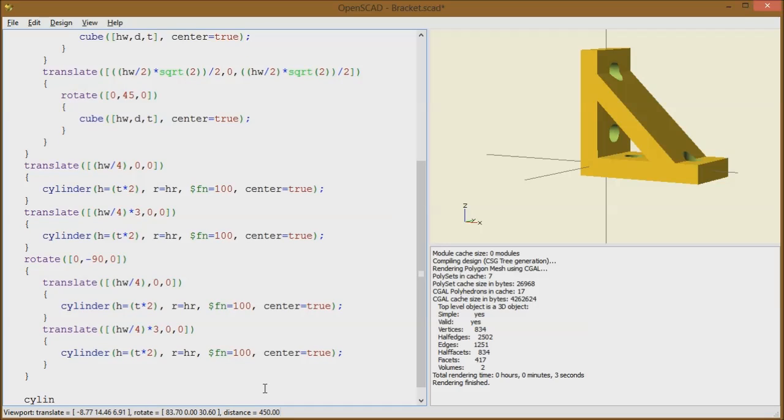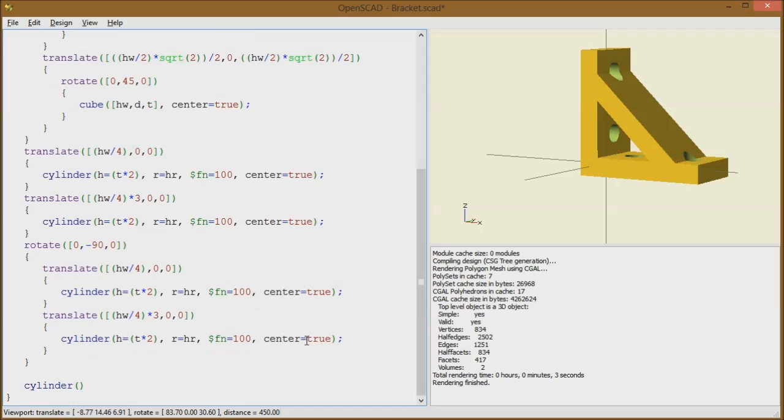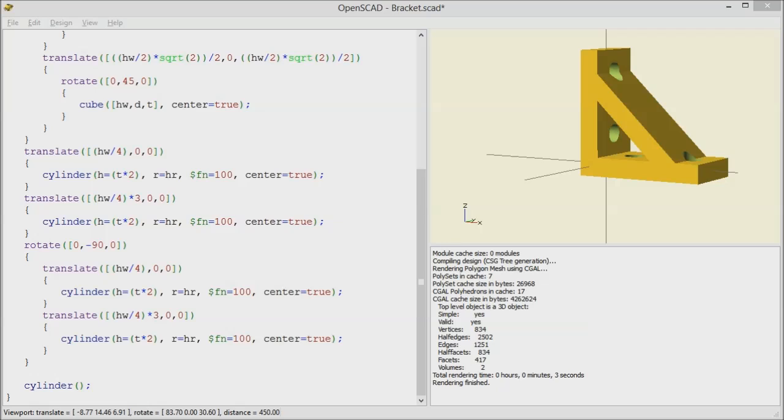So again, the way I do that is we'll start with a cylinder. Okay, let's get that slightly up. So a cylinder, remember to any command that you give it as opposed to a command that acts on something else, every actual object command has to end in a semicolon. So if we now want to put a slightly thicker cylinder, because obviously remember now not only the screw has to fit through there, but the screw normally has a slightly bigger head which sits on there. It needs to fit through.